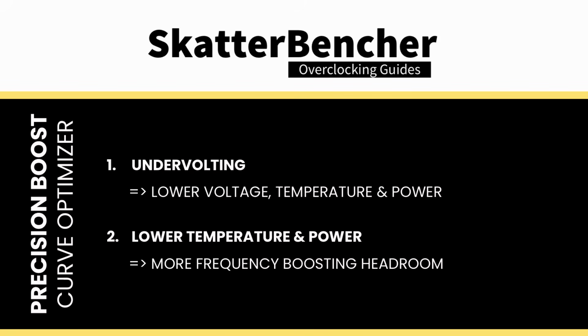That helps in two ways. First, undervolting lowers the operating voltage, temperature, and power consumption. Second, as a consequence, the Precision Boost 2 algorithm can leverage the additional headroom to boost to higher frequencies. So you tend to get lower temperatures and higher performance. It's a win-win. But there are a couple of caveats when it comes to tuning with Curve Optimizer.